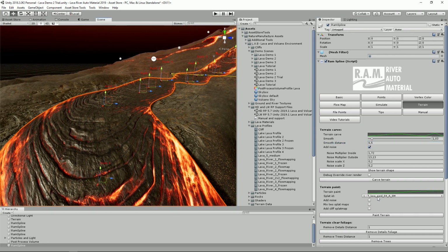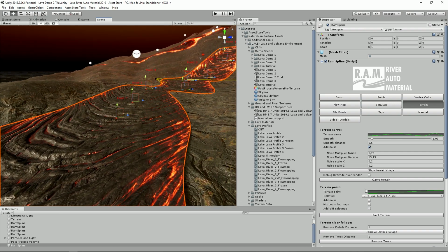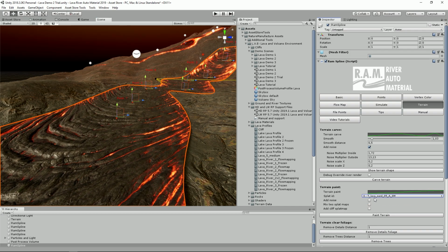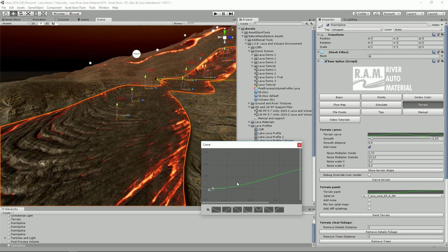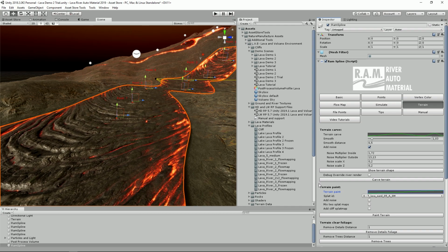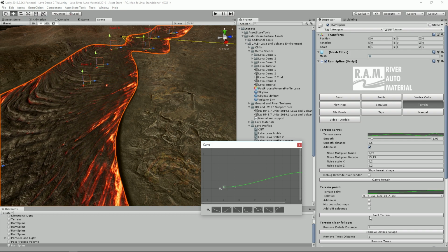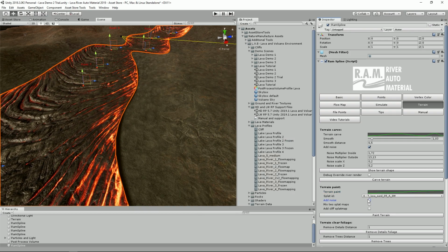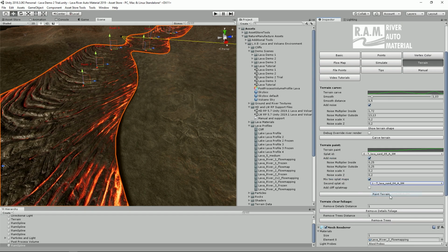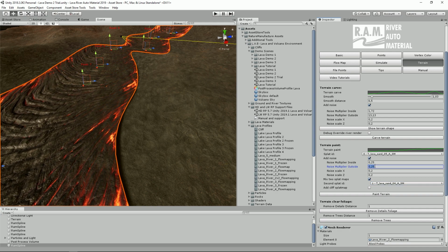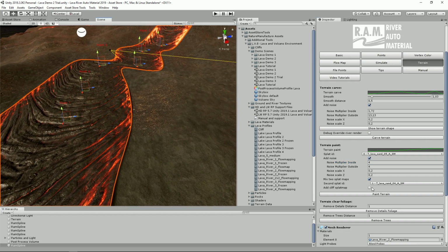If we could carve the terrain, we could also paint it with our spline solution. If we click paint and we choose a texture, it will paint it first. We could, of course, force it to paint outside the spline as well, as we see. So we have full control over the painting. There is also an option to paint with noises, so we could mix two textures, for example, like that. Maybe let's increase the noise power, and we see that it paints with noises as well.